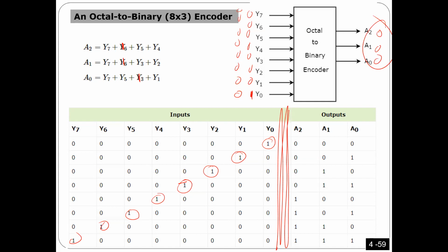We will do something like that in a minute. But to solve this problem, I'm going to introduce another output here. This output should give me 0 or 1. If you give me 0, that means there is no valid input. The word valid input means there should be at least 1 here.